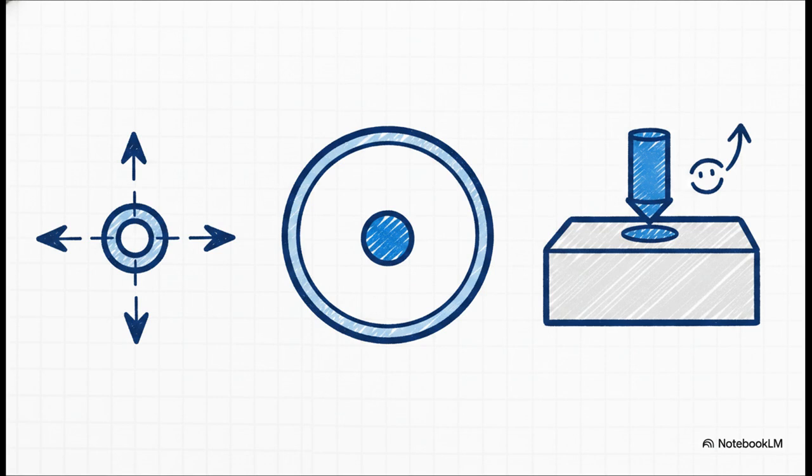As the machinist drills that hole a little bit larger, moving toward least material condition, they earn what's called bonus tolerance. That expanding tolerance allows the hole center to drift a little more out of position while still guaranteeing the bolt will pass through, and this directly enables the use of physical fixed go-no-go functional gauges.